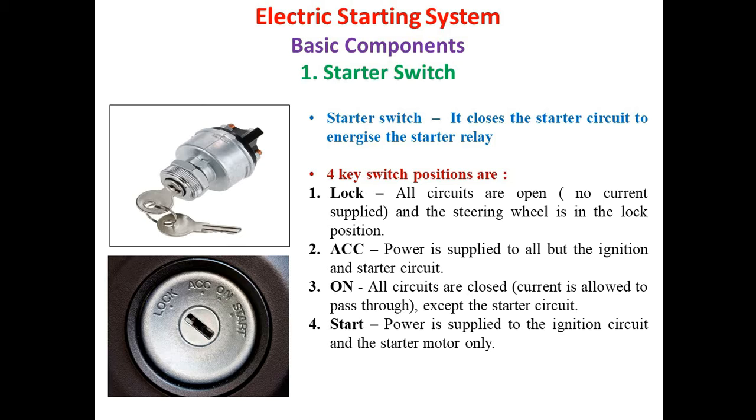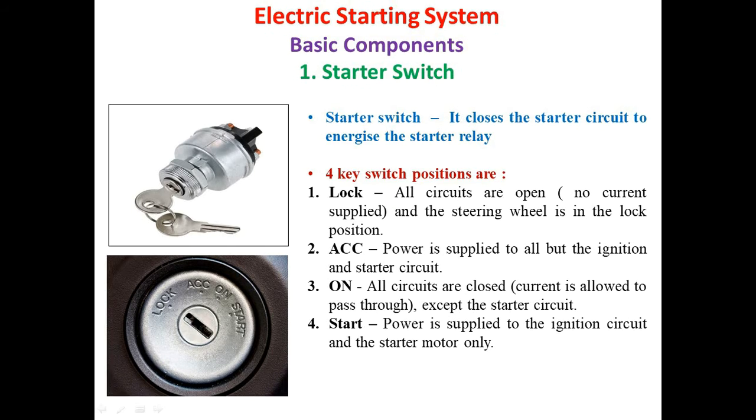The starter relay is nothing but one which controls the opening and closing of the circuit from the battery to the magnetic switch. Now, this starter switch has 4 key switch positions which you can observe in this photographic view. The first one is the lock position. In this position, all circuits are open, meaning no current will be supplied. Also, it locks the steering wheel.